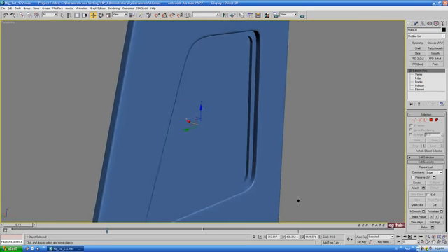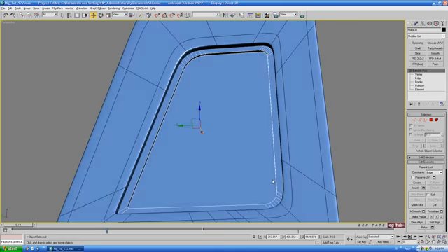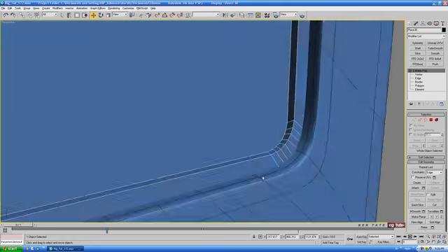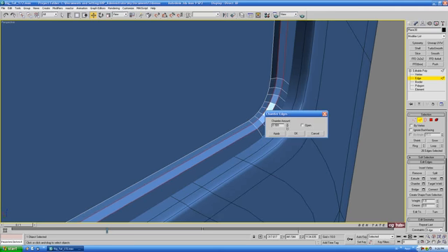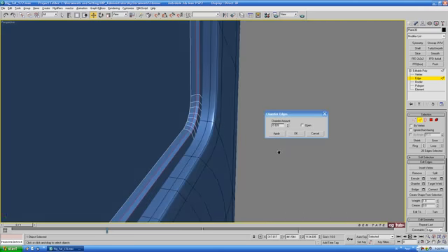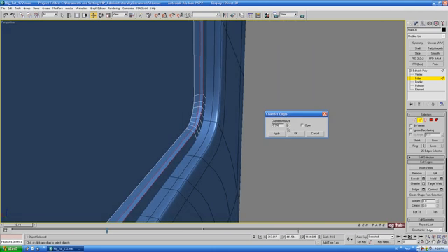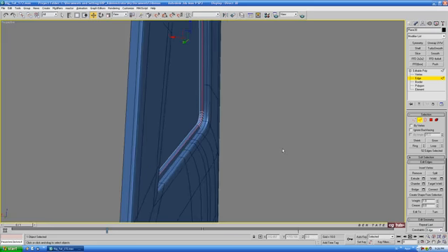Alright, that'll take care of the frame there, and let's also chamfer down the outer edge, just soften it up a bit more. So grab one of these ones here, loop it, and chamfer. Dial that back a bit. Maybe around 0.5 or so should be good, and okay.